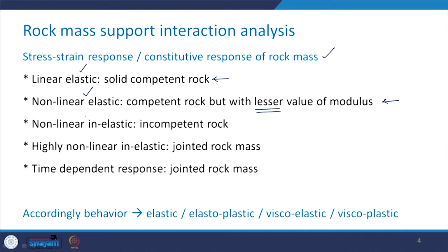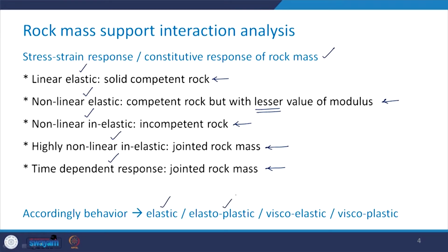It can be nonlinear inelastic in case of incompetent rock, highly nonlinear inelastic in case of jointed rock mass, and then you can have time dependent response also in case of jointed rock mass. Accordingly, the behavior of the rock mass would be either elastic, elastoplastic, viscoelastic, or viscoplastic.